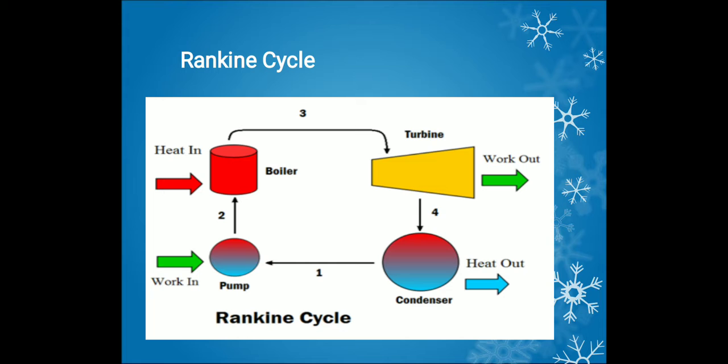Before that, the steam strikes the turbine blades. After that it passes into the condenser. In the condenser the steam is converted into water, that is, latent heat transfer takes place in the condenser. The water then passes to the cooling tower or some other heat recovery plant. Then the pump feeds the water to the boiler section.